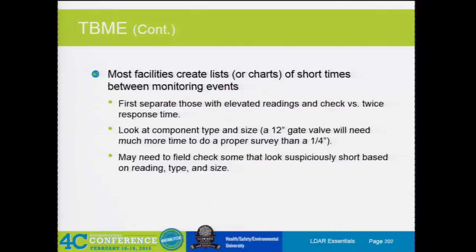We talked about this one. Another thing you can look at is the time between monitoring events. Like we said, we always have data. So another thing you can do is look at how long they are actually surveying the component. We showed you the LDAR monitoring period earlier today, and with that, you can go through and say, okay, this is a 12-inch valve. How long did he truly survey? Oh, he surveyed a 12-inch valve in 3 seconds.